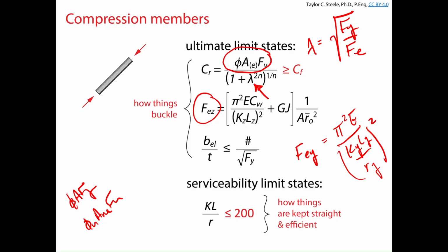So at least if weak axis buckling is going to govern, we know it's going to be something like this. We need to know the length of the member, and that's fine. We probably know that. We need to know the effective length factor, and that's okay. We can probably know that. But that's ry, right? So we need to know an ry. We need to know an A. We need to know how thin the flange and the web are relative to their plate widths. And so there are a lot of moving parts here. There's no straight shot to calculate A.